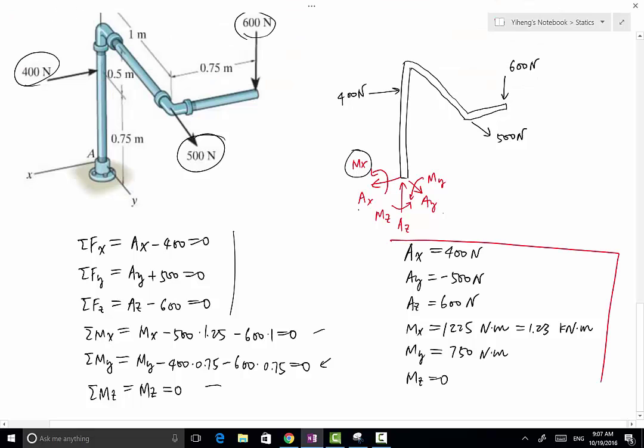As you can see, when I draw the unknown support reactions out in the free body diagram, I already draw them according to their conventional positive direction, so that when I solve for the unknowns, I can easily interpret the directions of all these support reactions.